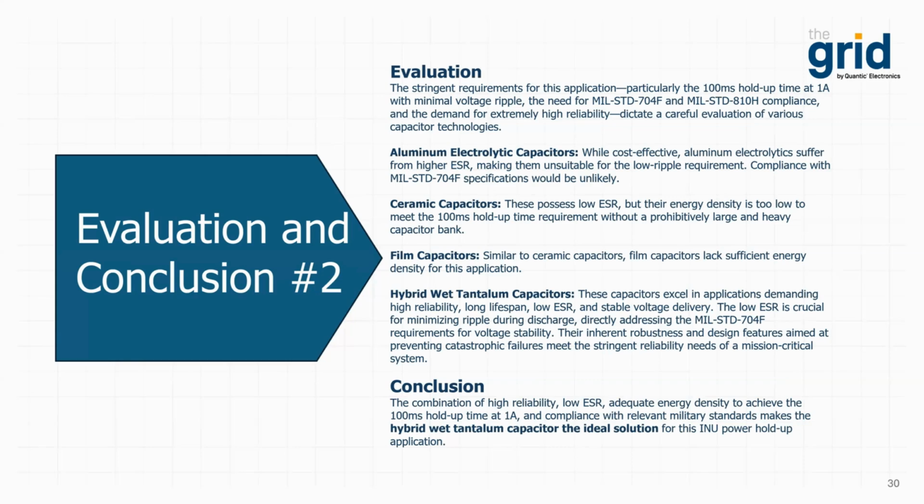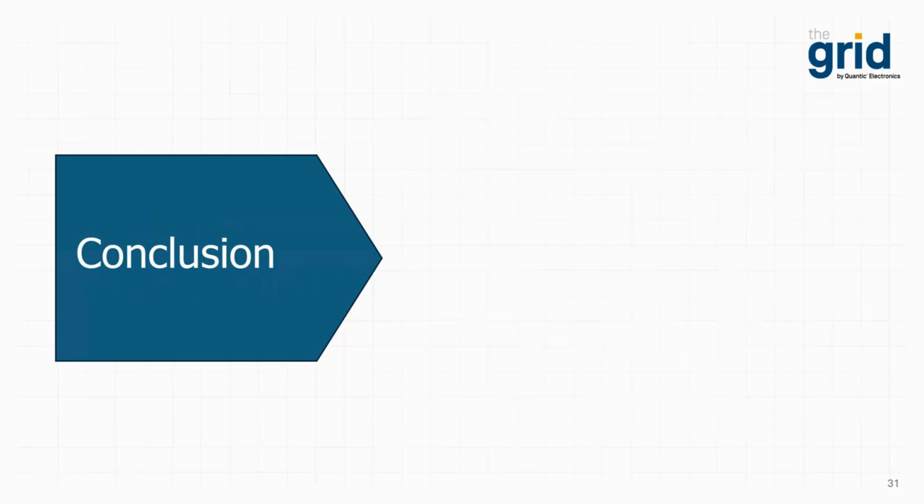This choice mitigates the risk associated with less reliable capacitor types and ensures consistent, stable power to the INU, even during brief power interruptions. Further steps would involve detailed simulations and testing to verify compliance with MIL-STD-704F and to optimize the capacitor bank design for size and weight while maintaining performance requirements.